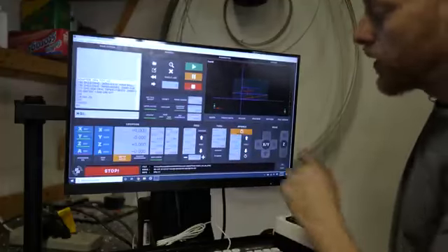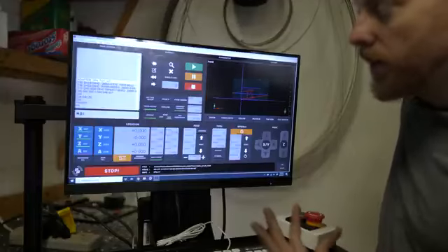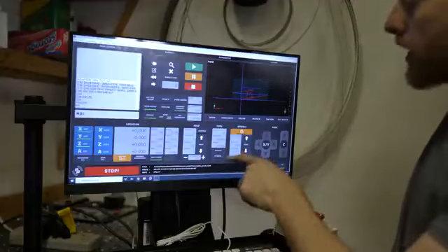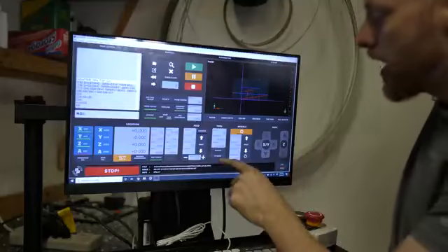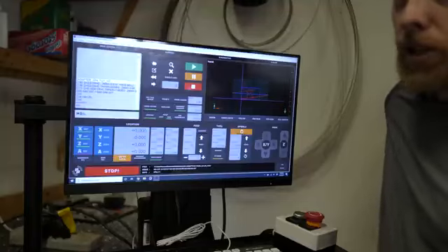Set that back. Tool height offset. This was set by the process of doing tool height offsets in the probing section. Coolant, this turns on and off the coolant. And M1 brake, that means it's going to stop between every operation whether there's a tool change or not.